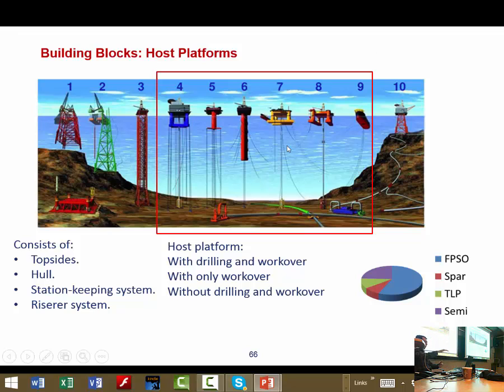But if you have a lateral motion of, like, 20% of the water depth, then you have a limitation for the type of riser. But here, for example, this concept which is shown here probably had very limited lateral motion because you have a dry tree system on that, because you have top tension risers or vertical risers. But the next solution is semi-submersible.